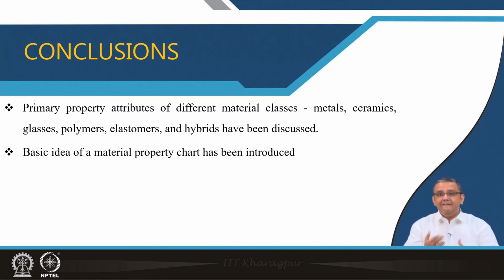To reiterate, if you want to develop a hybrid of metals and ceramics: metals typically have high density and high ductility, ceramics typically have low density, low fracture toughness but high stiffness. Combining a metal and ceramic in the appropriate design, dimensions or shapes can provide a material with a good combination of low density, high stiffness and reasonably high fracture toughness.